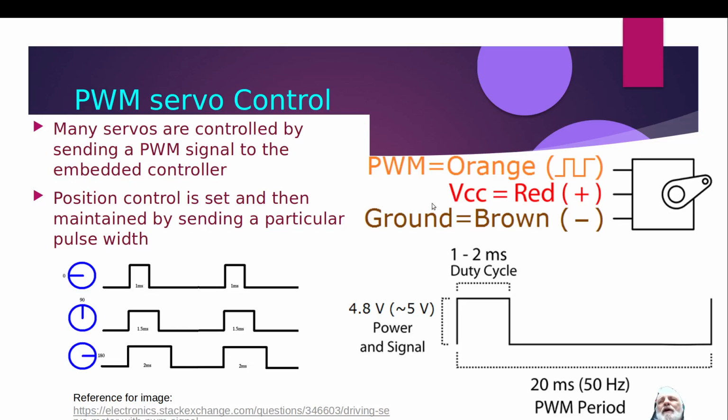All right, so for our analog servo motors here, again, we send what we call a pulse width modulated signal. You're sending what we call a square wave, or sometimes a rectangular wave because it's not perfectly square. Usually this pulse is running at 50 hertz, which means you have 50 pulses every second, or a pulse every 20 milliseconds.